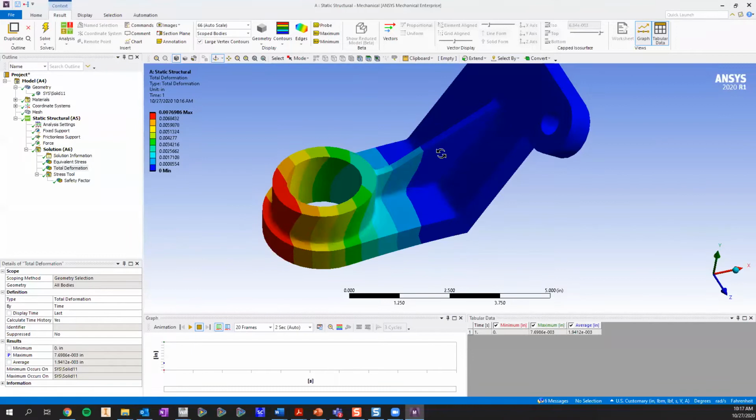I can use DesignXplorer to run a design of experiments and see response surfaces for me to understand which is the most optimal bracket based off of my own criteria. For today's criteria, it's going to be to minimize the mass, minimize the deflection, and have the highest factor of safety as well.